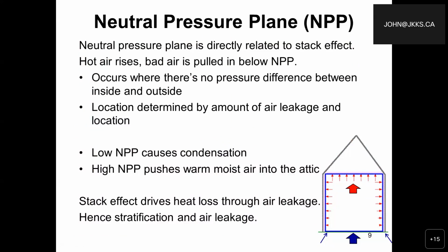And as the hot air rises, if there are potential areas of leakage, it wants to pull in the air from outside of the house through these open joints, or air leakage locations within the house. The neutral pressure plane occurs where there's no pressure difference between the inside and the outside, and the location is determined by the amount of air leakage in the location.